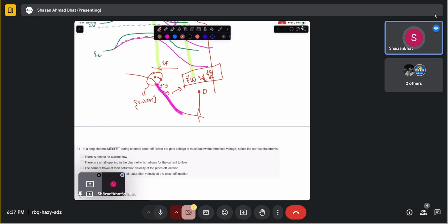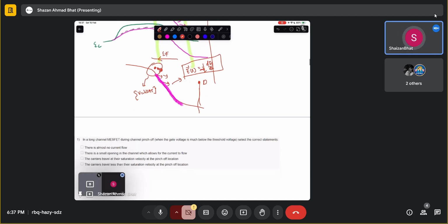That means the electron will go down the hill, and because it's a very steep slope, it can cause other effects also. Let's say it can cause impact ionization, which we have discussed in the previous section. Because of huge kinetic energy, it will hit other atoms and knock out electrons. One electron will give two electrons, this will give four electrons, and so on, and the cascade reaction can happen, and you have certain breakdown mechanisms. But there are other mechanisms to tackle those regions.